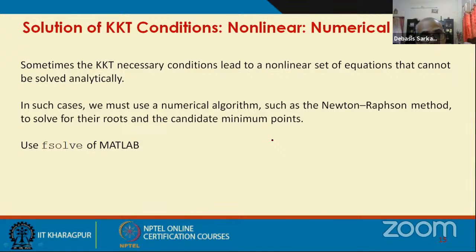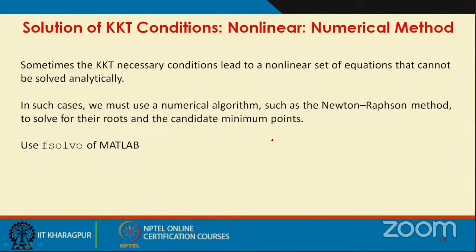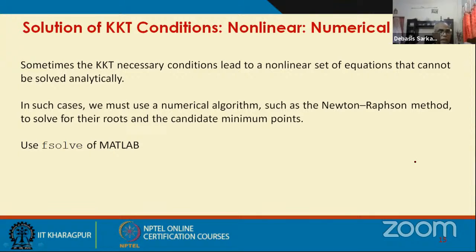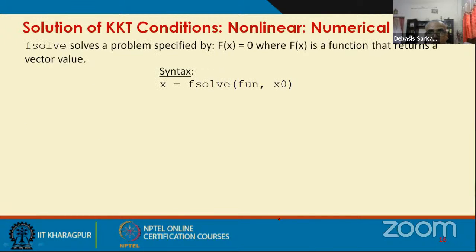For the purpose of today's session, let me show you the use of the MATLAB function fsolve for such cases. We'll take a simple example where, after applying these optimality conditions, we have, let us say, a set of 4 nonlinear equations which need to be solved simultaneously.